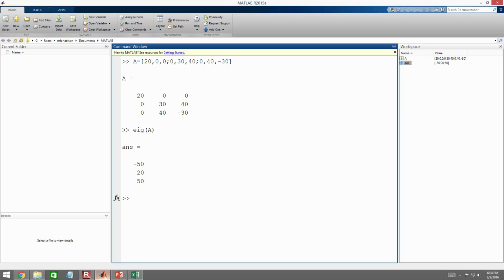The second type of analysis that I want to teach you all is a buckling analysis. In other words, things in tension will just tend to stretch, but if you have a slender element, you cannot take the same force in tension and expect it to behave exactly the same in compression, because things in compression like to buckle. Okay? So what we want to do is determine how to calculate buckling loads, which are essentially eigenvalues as well.